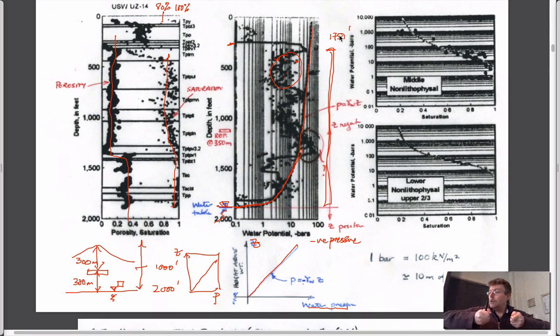And if you could hold this column of water, the pressure, or the stress, that you'd have to apply to physically hold this up by its bootstraps would be this magnitude of pressure that you're seeing here. If you have a column that is only roughly 1,000 feet high, then the pressure you have to apply is only this amount, and it would be equal to rho g z: density times gravity times the height of it. So it's not saying anything other than that this curve is a linear curve of pressure versus elevation.